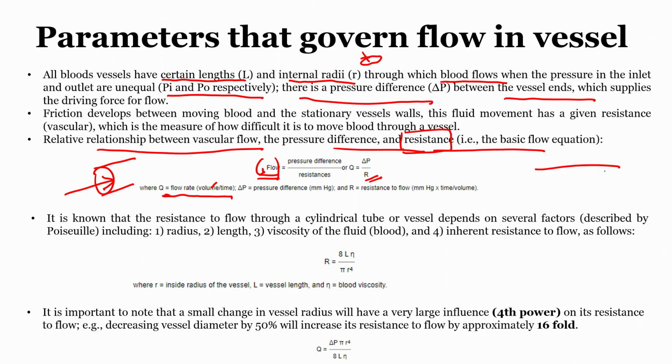Now, when the fluid is flowing through a channel, it assumes a flow something like this. The flow is parabolic, a structured flow like this, because the walls of the channel have something called wall shear stress, which offers resistance to the fluid flow. Considering this parameter, the volumetric flow can be calculated as the ratio of pressure difference to the resistance R that the walls of the tubular structure offer.